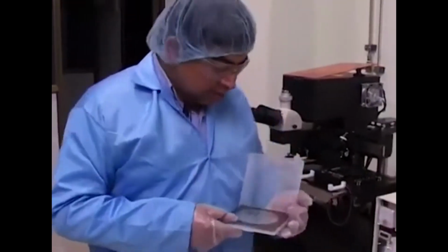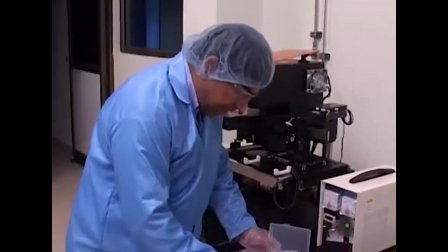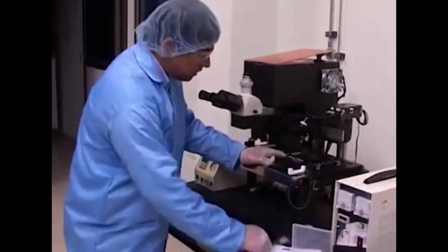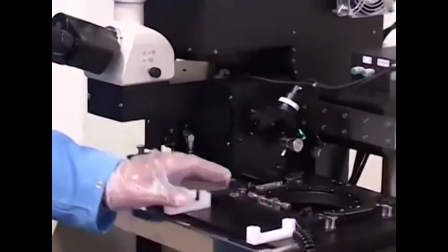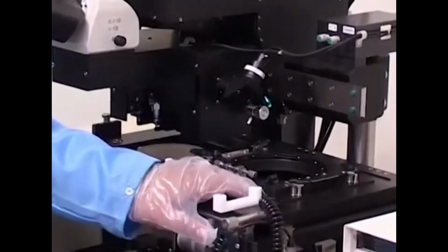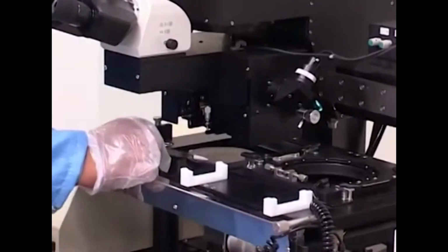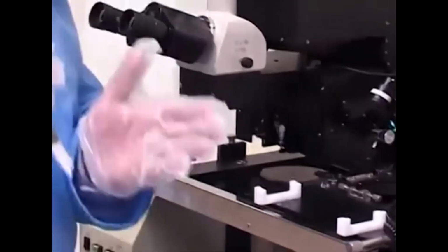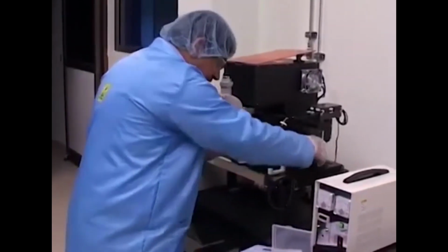So what I am going to do now is tell you how to use the lithography setup to actually do alignment and exposure. Here we have something called a mask holder, which is this region here. The mask sits on the bottom side of this holder, facing the wafer, which would be placed somewhere here. This is the wafer stage, and the idea is to precisely align the hard mask over the wafer surface. In order to do that, we loosen these particular points here.